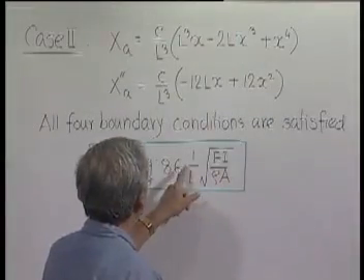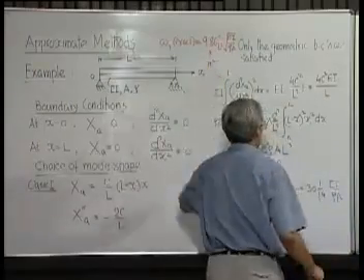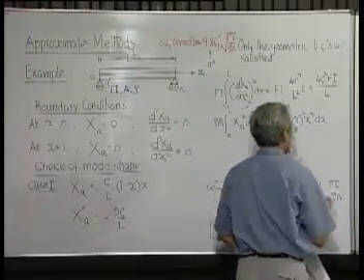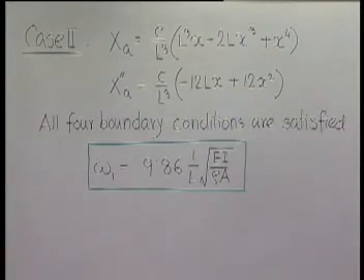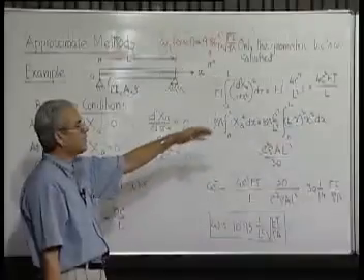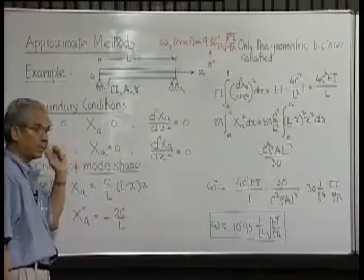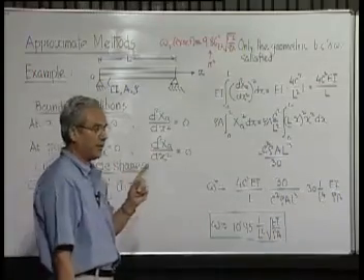If we do it, we will find this will be slightly higher than the first natural mode we find by the exact method. So whatever value we get by Rayleigh's approach, as we have shown earlier also, is always slightly higher than the exact value.